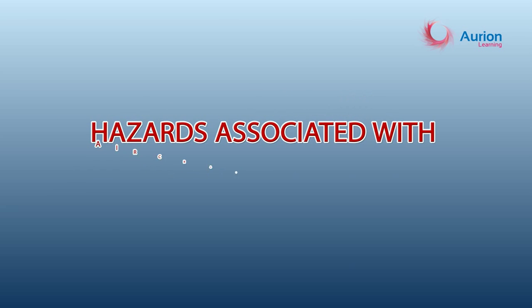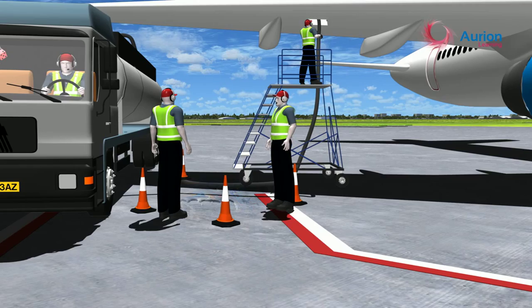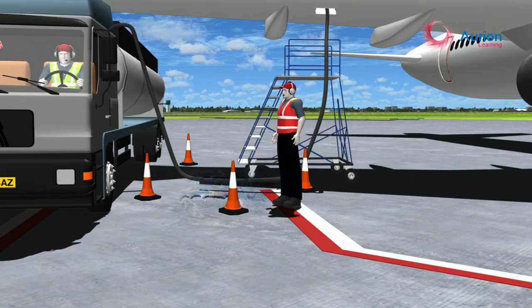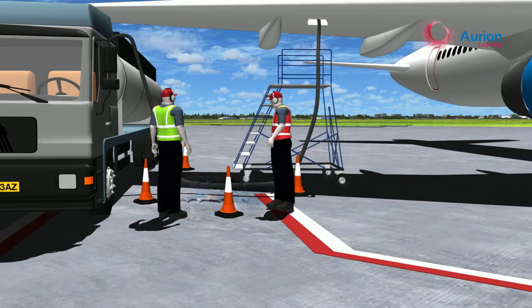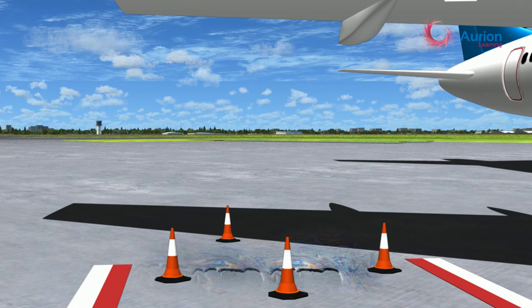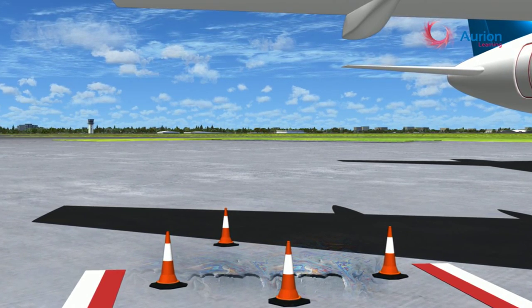Let us now take a look at some of the hazards associated with aircraft fueling. Fuel spillage is a serious hazard that affects airside safety. If you come across any fuel spillage incident, report immediately to the apron control for necessary action. The operator that caused the spillage must switch off his engine and remain with his equipment until the substance is cleaned up and the area is safe. Cordon off the area of fuel spillage so that no vehicles or equipment can drive through it.